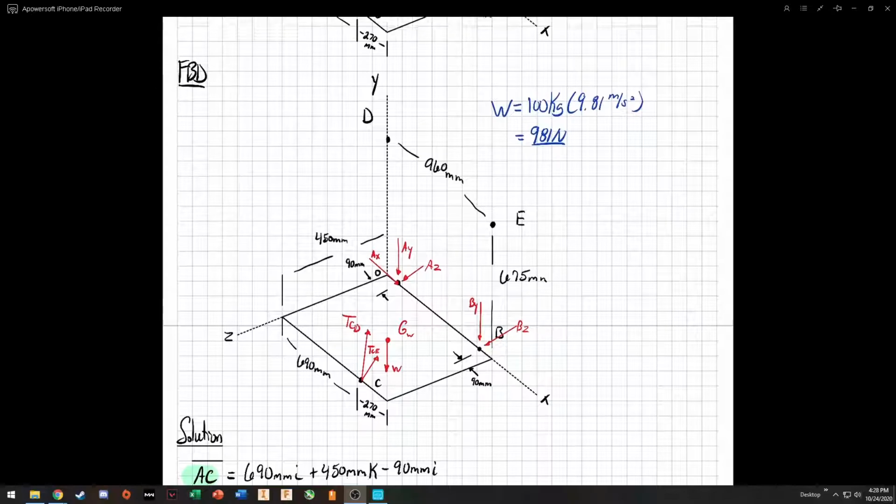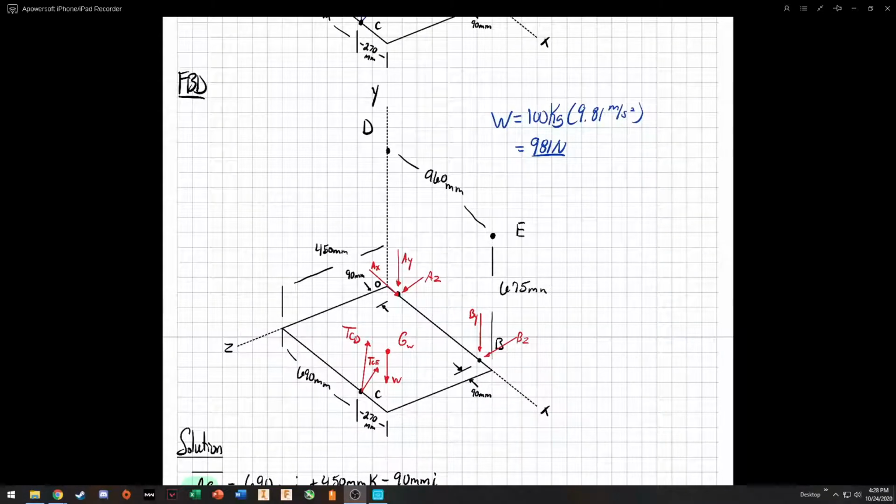Starting right along, we'll go to the free body diagram. We have the hinge at A, which exerts all three forces. You can state the y direction to be positive up or negative down. When you put your reactions at A and B, you're assuming a direction. For this problem, because it's kind of hanging, the tension's holding the plate up, I assume that the reactions are going to be down, at least in the y direction. So I have AX, AY, and AZ, AY being negative, and BY is also negative, and we have BZ. We have nothing in the BX direction.